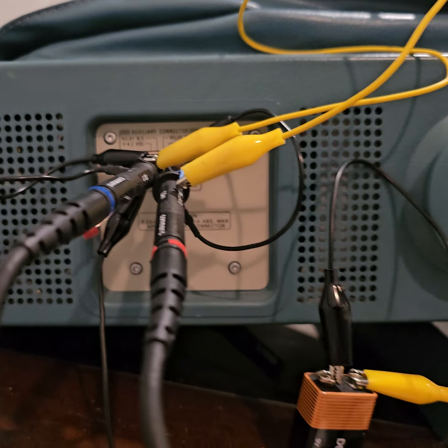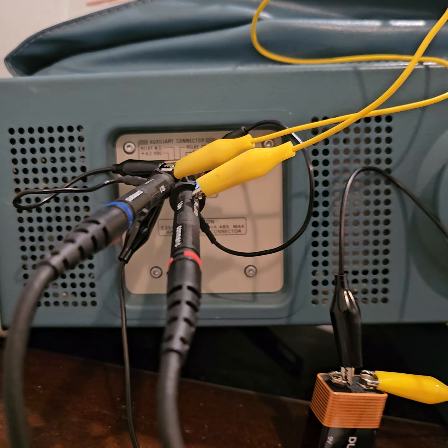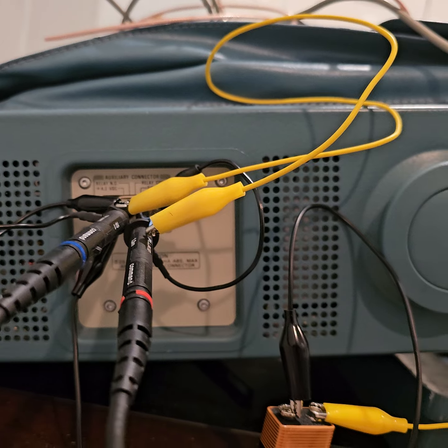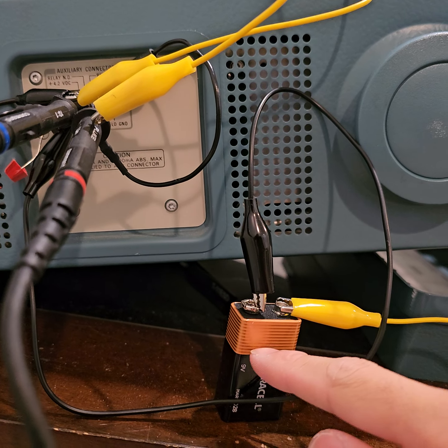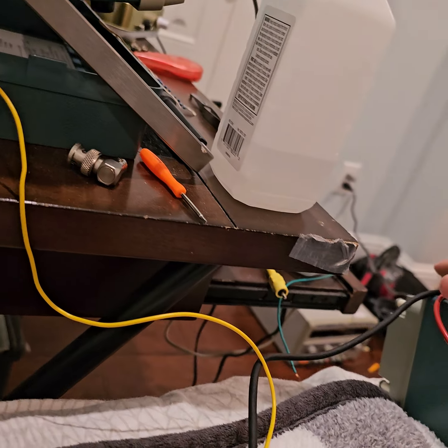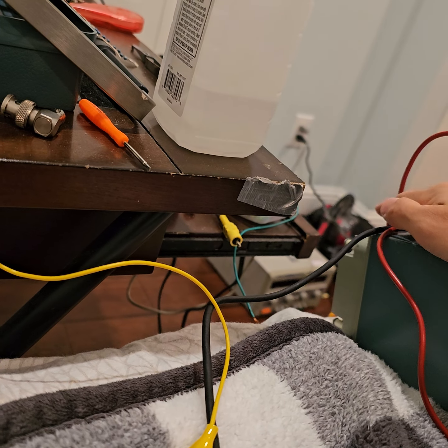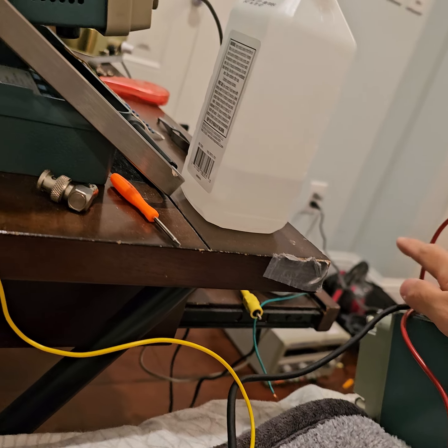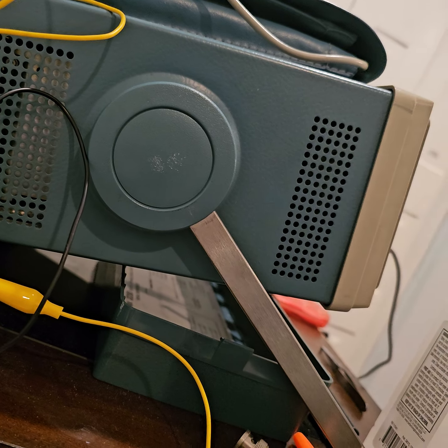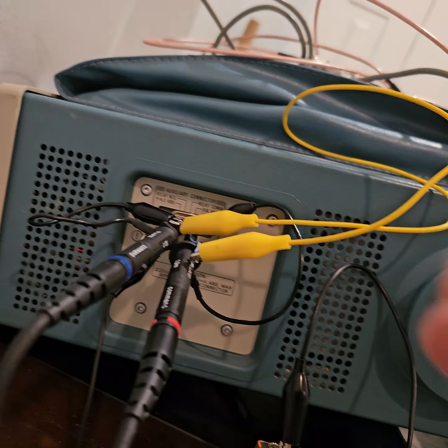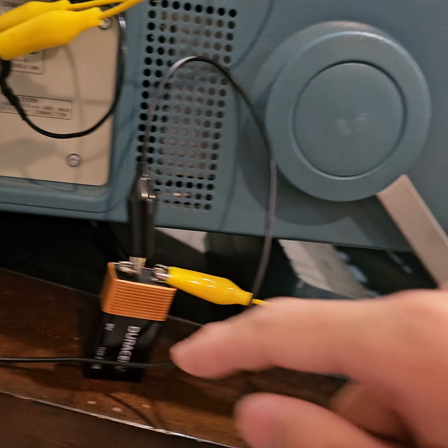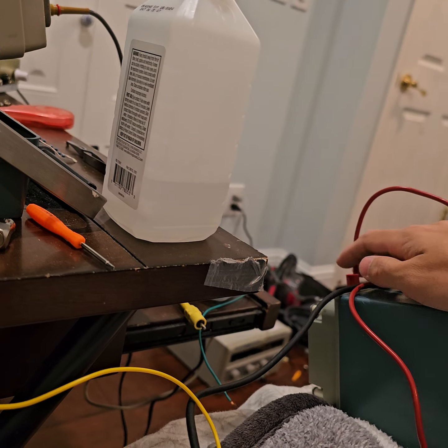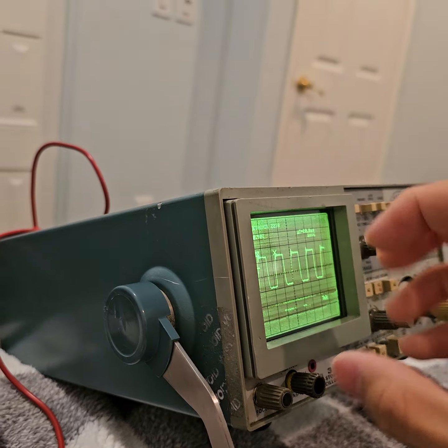So when it's not wanting to make a beam, when the beam is off, the relay is closed, which sends the voltage from this battery into the z-axis, a positive voltage, so it blinks the beam. But when the oscilloscope wants to draw a beam on the plotter, the relay is open, and then this disconnects the battery from the z-axis, and then the beam can write again.